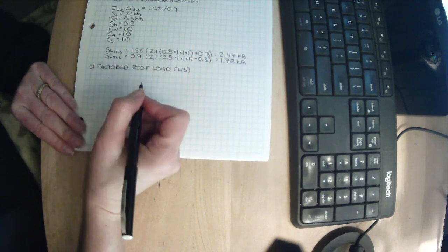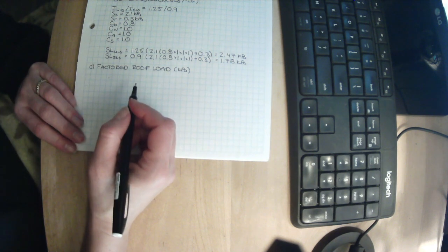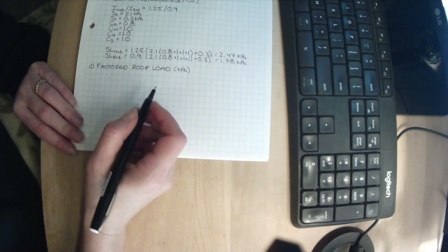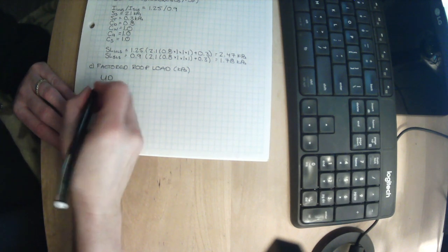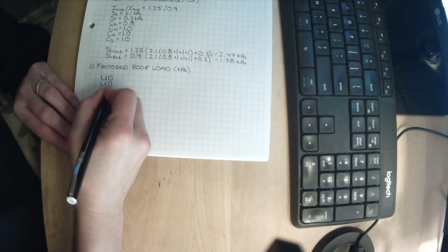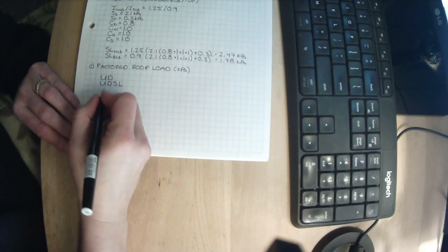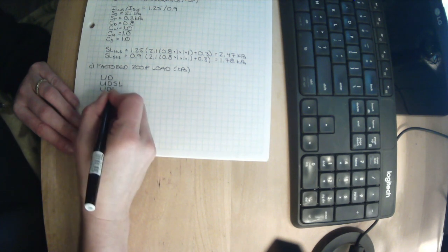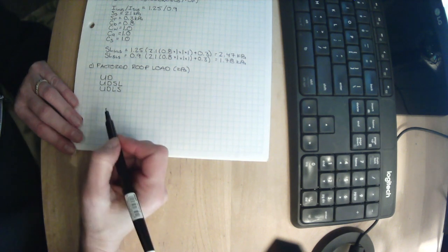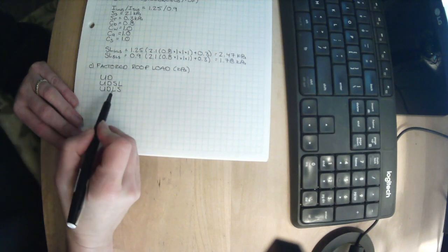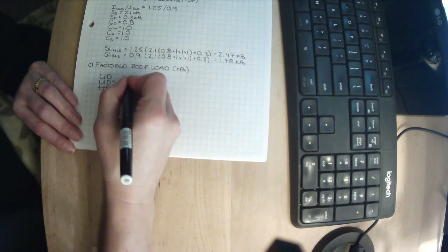All right. We're going to have our ultimate limit states load combinations. And remember, I always put a little U in front of it to remind myself of all the combinations I'm thinking of. We're going to look at our ultimate dead case, our ultimate dead snow, and we know that there's a companion load of live that we'd need to worry about on there, and ultimate dead live snow, with live as the main case and snow as the companion. Now, here's the thing, we have no live load. So live load being the primary load case, I'm not even going to calculate it.